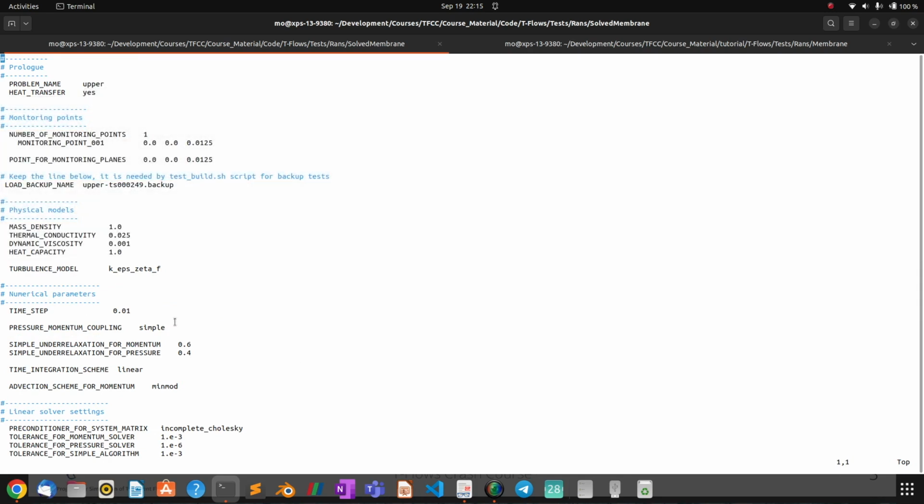If you want to constrain the problem, or if you want to make some details in the problem about turbulence modeling, some convergence criteria, some tolerances between pressure and velocity coupling, you need to specify these details that you want to impose on your problem as a set point. Apart from that, you always have backup control parameters that will feed this control file to make it a smooth process.